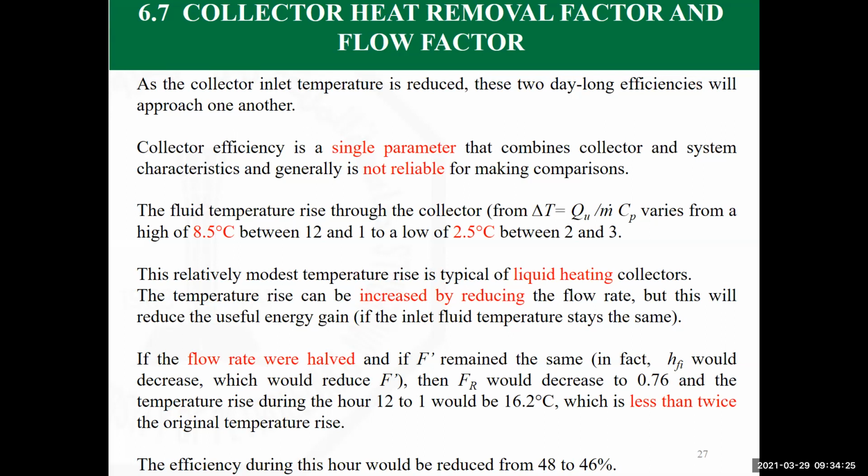This is on one hand. On the other hand, water can carry the energy more efficiently than air. We have problems in our systems where I connect the air, air comes into the solar collector, and I get the air out of the solar collector at a very high value, 100 degrees centigrade, where I needed only 80, so I get 100 easily. But at any bend, at any expansion, the air loses this energy very easily. Water is difficult to heat compared to air, but it keeps the energy in.